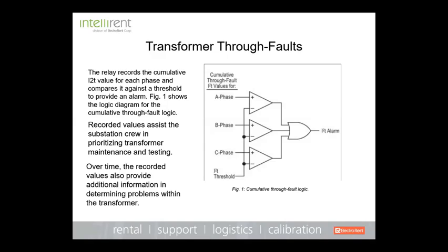For instance, this happens not just in high voltage situations, but in distribution systems, distribution substations. If you have a large number of through faults, maybe not to a magnitude that would do any damage, that could indicate that you may have some maintenance to do out in the distribution circuit, in terms of tree trimming or things like that.